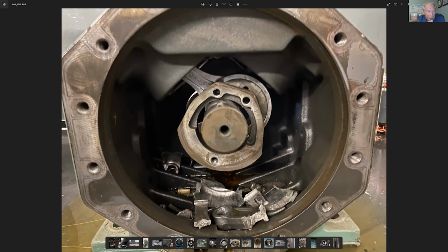One thing, Kevin, I was thinking also, and looking at this, you were talking about how to distinctly tell the difference between a loss of oil and a slug, and sometimes it can be a little difficult. But if you can get that crankshaft out all the way and inspect all those bearings and journals, generally with a loss of oil, you'll have a very even wear pattern. The front bearing, the journals, the back bearing, everything is going to have a pretty even wear pattern in a loss of oil situation. With slugging, the refrigerant may pop up by just one journal and one cylinder, and you're good in the front, you're good in the back, but it's that center journal where the rod hits onto the crank.